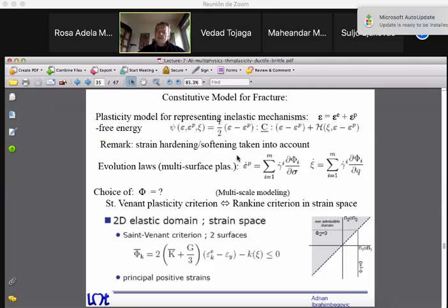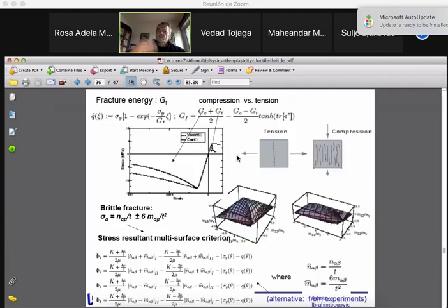And then you turn this elastic strain into the stress by multiplying with the corresponding mechanical properties. The K is bulk modulus, G is the shear modulus, and you provide the yield surface in the standard format. In particular, you have here two yield surfaces. You have for the first principal strain, and then you have for the second. But please note, the first principal strain should always be equal or bigger than the second. So in fact, the real active yield stress is this for the first strain, and then the second one reduces only to a point. So this way, from the strain field, I can put into the stress field.